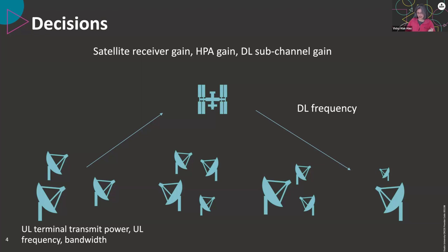From the uplink side, we have the transmit power that we can adjust or optimize. Then we have the frequency and the bandwidth; the power together with the gain will give you the EIRP. Then when the signal is transmitted to the satellite, there are the losses: the pointing loss, atmospheric loss, implementation loss, and a lot of other losses as well.